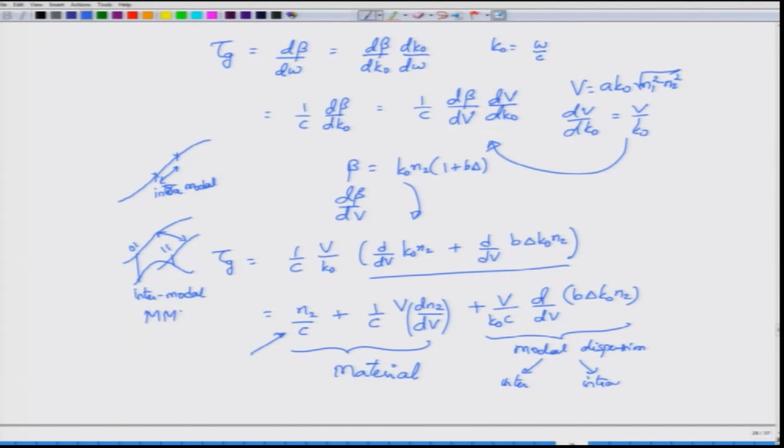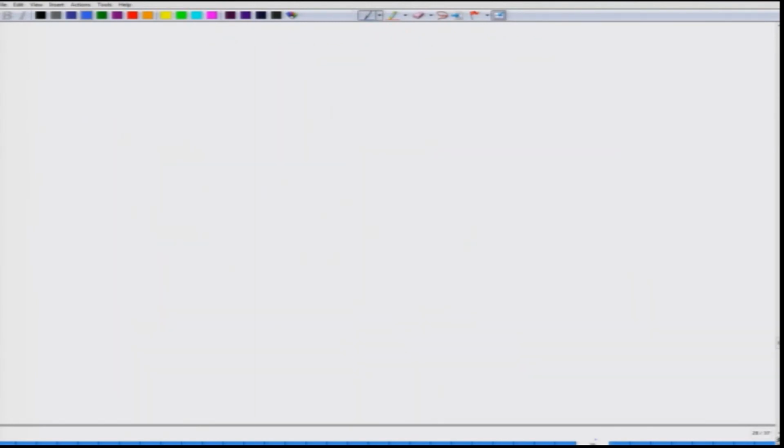Intermodal dispersion is quite common and in fact is one of the major problems in multimode fibers, whereas intramodal dispersion, sometimes called simply chromatic dispersion, is an important parameter in SMF. But our formalism would simply want you to know what beta 2 is, and therefore does not really depend on whether you have applied it to a single mode fiber or a multimode fiber. But it is interesting to see that this modal dispersion comes because of 2 effects, as I have told you.